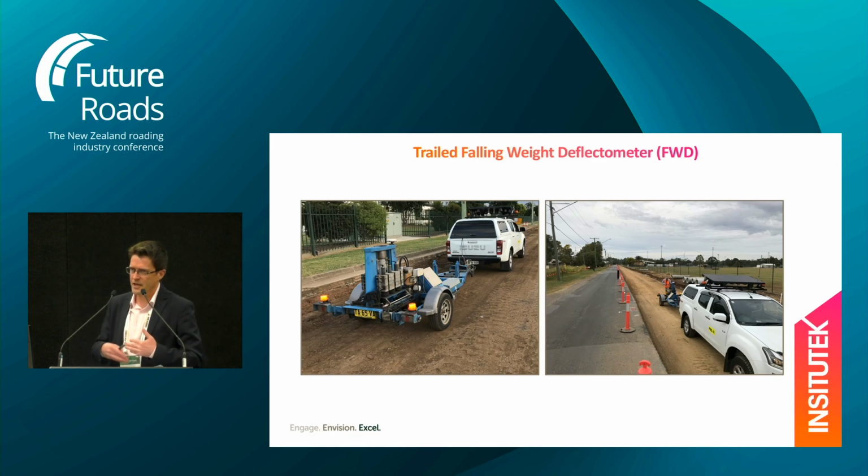And these are layers which are more difficult to test with a lightweight deflectometer because you don't generate enough pressure and deflection on the pavement to get meaningful information. So each method has its role to play.